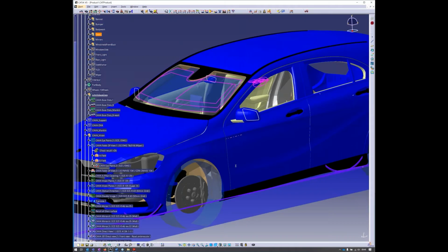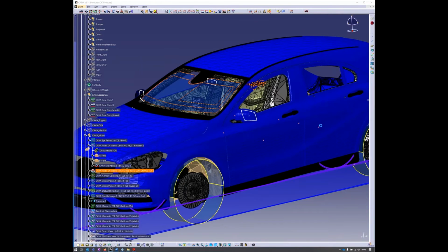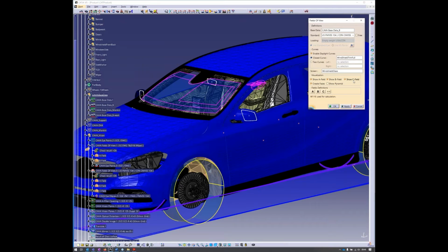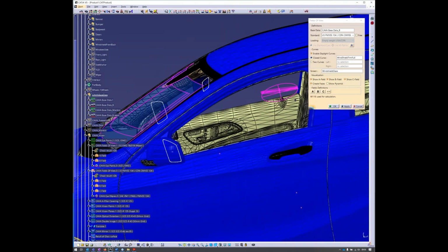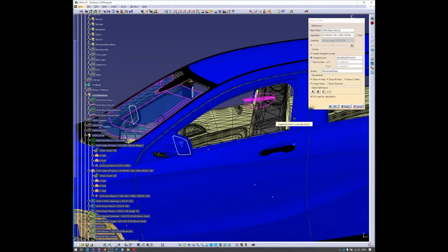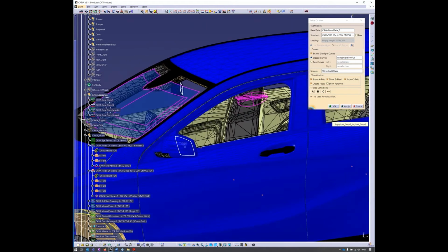There are small differences. On one hand, there are three fields, A, B, and C field, but also you will notice CAVA has not created an eye point, but a so-called eye ellipse, because the US standards usually use eye ellipses as the input to derive eye points for a specific purpose. CAVA will always use the correct eye points or eye ellipses as required by the standards and makes use of them accordingly. Like in this example, the angled planes that make up your vision fields will be tangent to these eye ellipses.